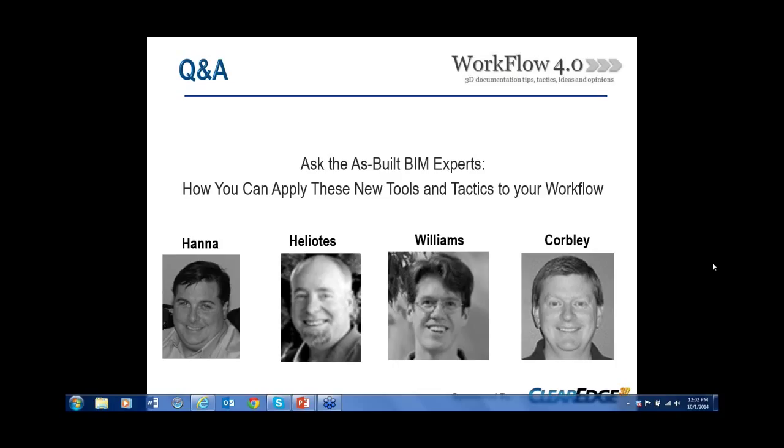Okay, great. And Mark, here's one for you, but I'm going to let Chris chime in as well. But Mark, you go first on this one. Really interesting. What process are you using to verify point cloud alignment with survey control? And is this process communicated through the Revit model? Great question. We're verifying point cloud alignments in our point cloud registration software. So for this project, what we're doing is bringing in the external reference coordinates, and then comparing that fit to the sphere fit in the point cloud, and then just doing a verification on what the error is. We're not doing any of that in Revit. So that's all taking place before any of the point clouds are converted to Recap.